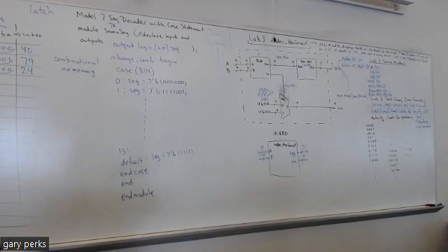Okay, the single bit output indicates whether the summation of A and B is even or odd, if the summation is greater than 15. The output is a 1 if odd, and 0 if even. If the summation of A and B is 15 or less, the single bit output indicates whether the A input is divisible by 4. The single output is equal to 1 if A is divisible by 4, and 0 if A is not divisible by 4.